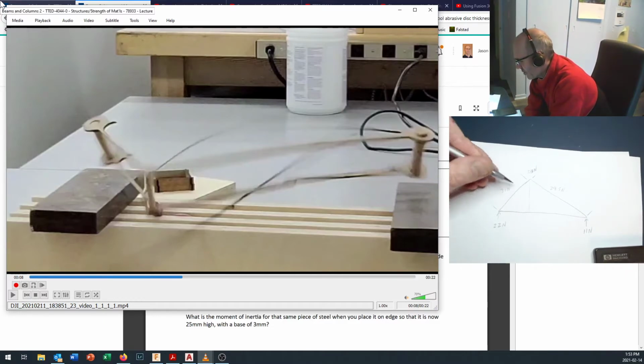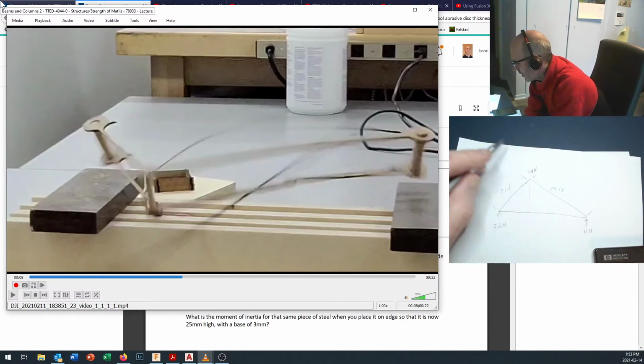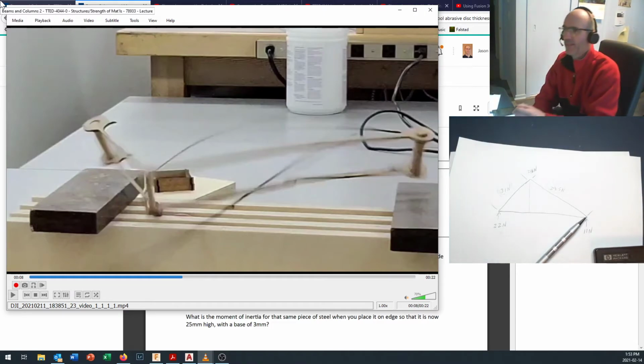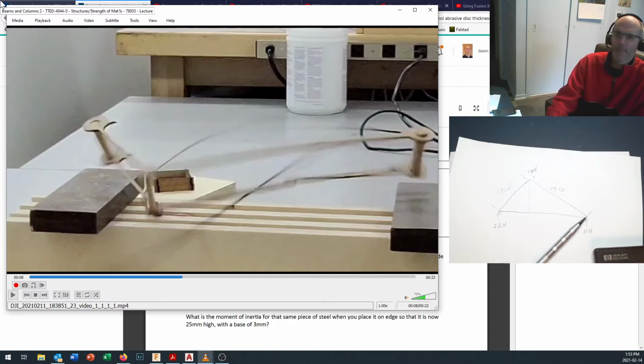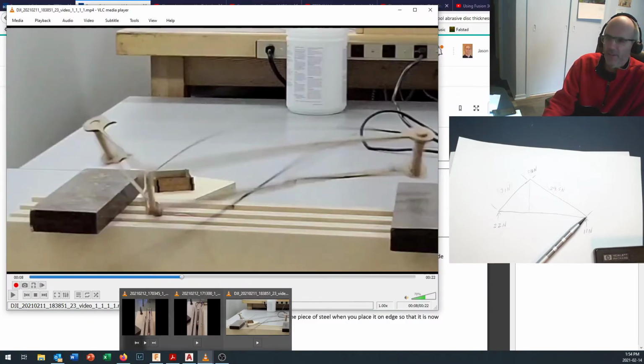So this was actually pretty close. We said that this side should be able to hold at least 27 newtons, and the most we were able to load it up to before this side buckled was 31 newtons. But over here, this was supporting 24.5 when we thought it should have only supported 17 based on our theory. And that's where these tests came in. And observing how it failed was so important.